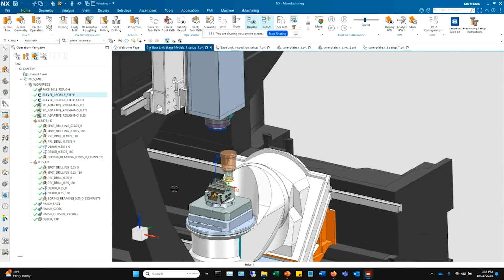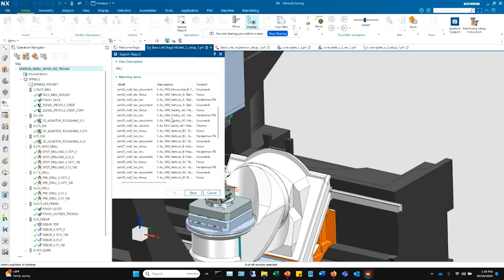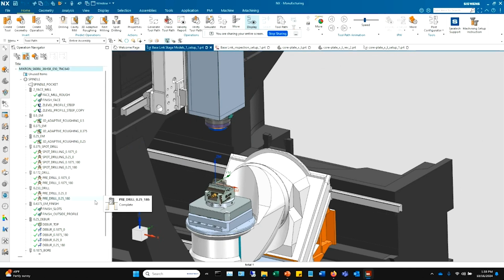Now, when it comes to the Saratech digital thread, we've taken all of this and built it into a template to where I can ask the software to interrogate the model, go to our libraries, pick the correct fixture, pick the correct tooling package for that particular material, cycle through our extensive library of machine tools, pick the best one that fits, and start the setup. Then it will run the feature-based manufacturing interrogation, and it will kick off going out to our libraries and our digital thread to complete the program. And I will be showing you an example of that shortly.